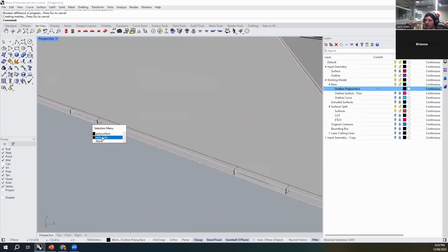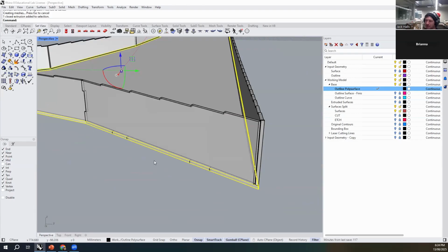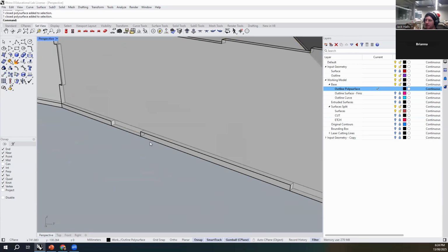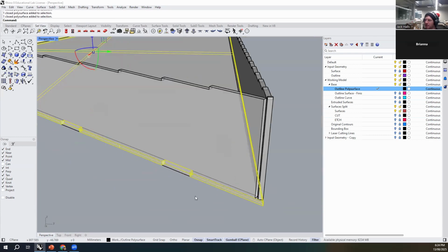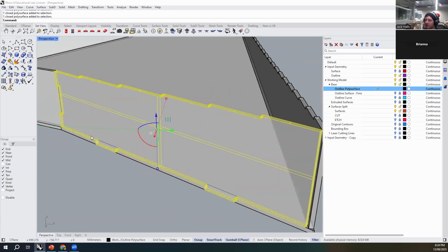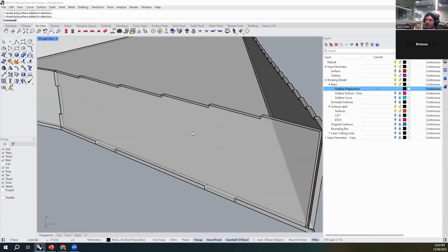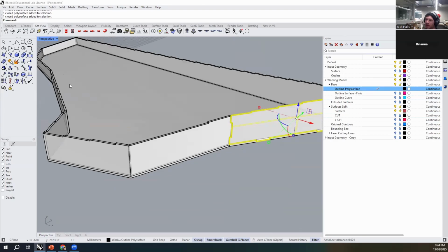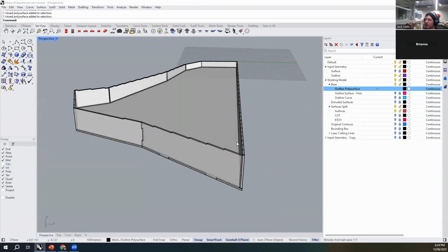Right now, it does duplicate things. So sometimes I'm doing different, so I'm just going to delete the input geometry there. And you can see we've got two geometries. We've got our base plane with those notches cut out, and we've got our side plane with those positive notches. So that is what you would again need to do all the way around for each edge in order to make that connection.